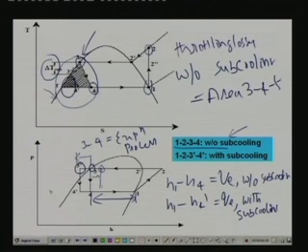So subcooling is desirable from this point of view also, because it ensures good and proper operation of the expansion device. The third benefit is that, if you remember from your last lecture, at the exit of the expansion device, which is nothing but the inlet to the evaporator, you have some vapor plus liquid, and that vapor fraction is given by X4. The larger this length, the higher the amount of vapor. When you are subcooling the cycle, the vapor fraction has reduced from 4 to 4 dash, because X4 dash is less than X4. This is also beneficial.